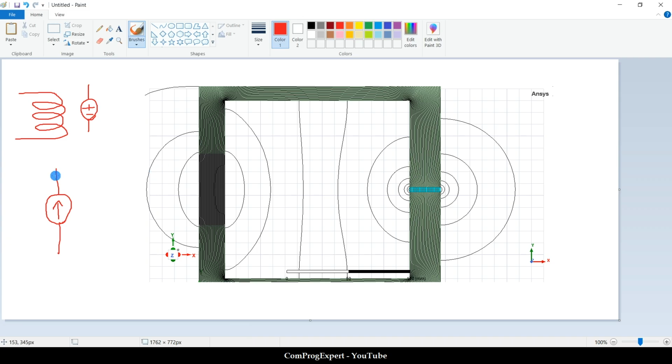And also here you added a reluctance, right? The reluctance of the iron part in the coil, here we can have this reluctance in parallel with this current source to model the leakage flux, right? This amount of the flux is leakage one.